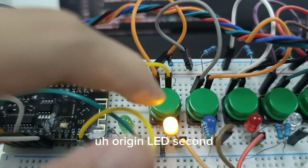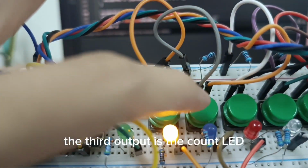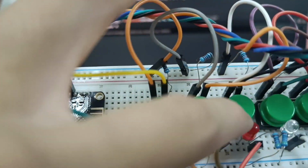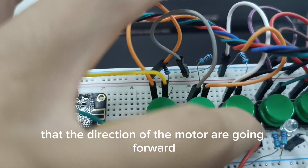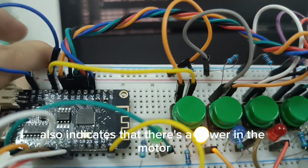Now for the outputs. The first is the run LED, which indicates that the motor is running. The second output is the origin LED, which indicates that the position of the motor is at origin, which is 0. The third output is the count LED, which indicates that the cycle is complete, and the direction LED, which indicates that the motor is going forward. And there's a PWM LED, which also indicates that there's power in the motor.